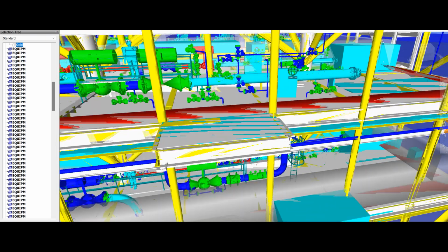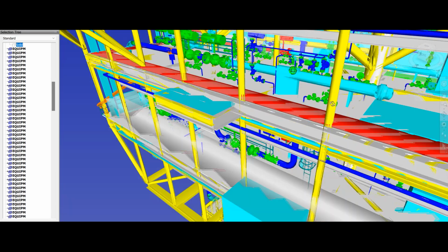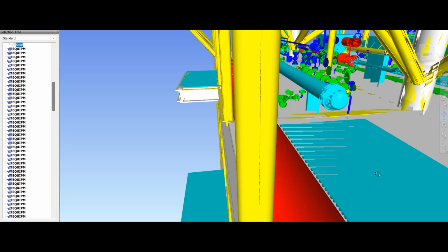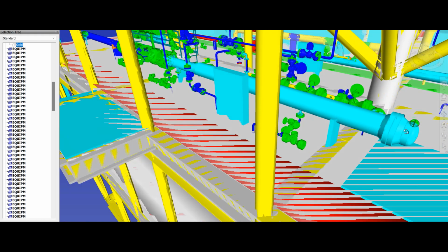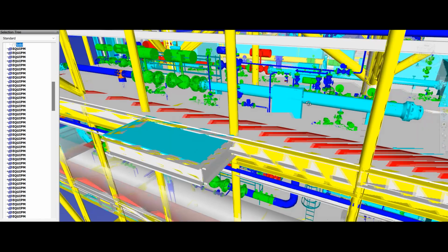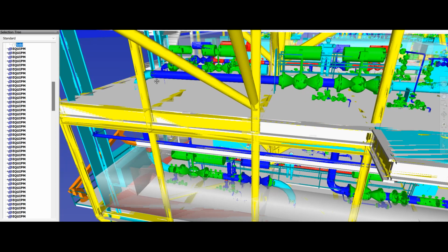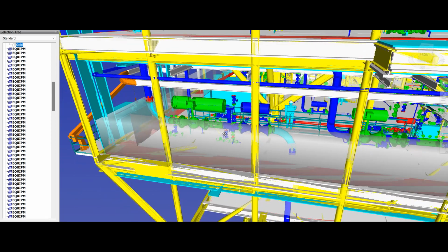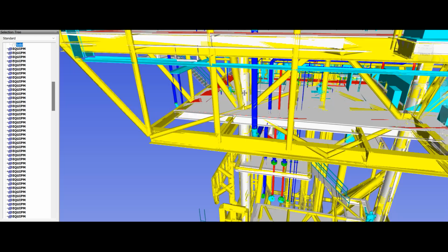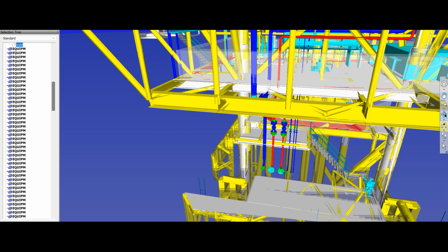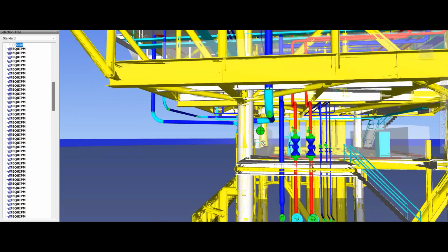So this is the launcher. You can see these are the block valves for the launcher. So here you can see this is the reserved space for the pig launcher. Now in the side view you can easily see the launcher, and now you will see the line from the launcher, it's going down, see, on the lower deck, and from the lower deck again the isolation valves are there, and then the line is going down further, and I'll show you where it is connected with the riser.